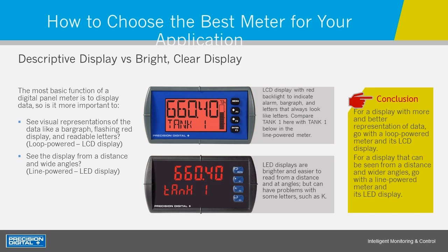Now you compare that with what you have on the ProView, and sure, I still got my 2 lines, so I still know I'm looking at 660.4, but it's a little less descriptive. It lacks the bar graph, it lacks the percentage. Another nice feature of the loop leader is because it has the ability to be backlit, we can make the entire display change color. On the ProView on the bottom, you've got red LEDs. That's what you have. On the top, you've got the ability to have a red flashing backlight in alarm conditions and a white backlight during normal operation.